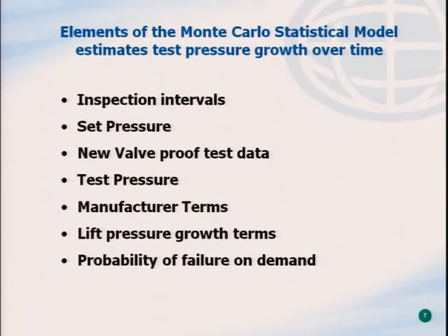And the valves in service actually follow a different distribution, somewhat different from the new valve database. So what I do is I developed a model from the new valve database, and then I placed that very same model in the used valve database to give a representation of the valves that I actually have in service.